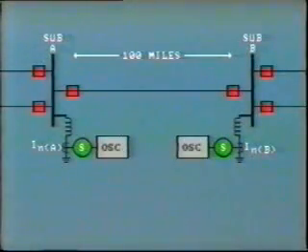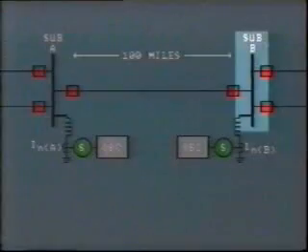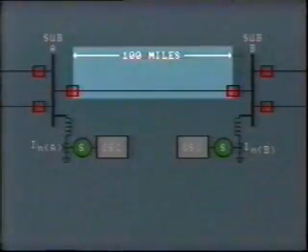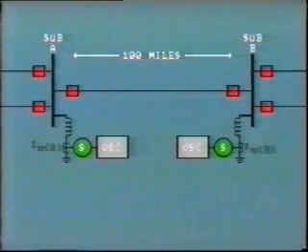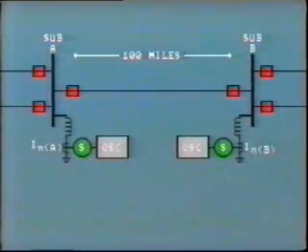Here's an example of how oscillograms, along with some computer simulations, can help pinpoint the location of trouble areas along a transmission line. The system one-line diagram shows 2 substations, A and B, separated by 100 miles of line. Both stations are equipped with oscillographs that monitor transformer neutral currents INA and INB. This installation suffers a particular problem.